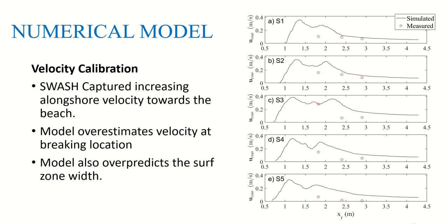And one important piece of information we have to state here is that the model is not perfectly simulating the real case in the lab, because the SWASH model simulates only a fixed bottom, whereas in the lab we were examining movable beach slopes that can have an effect on the results. Also, the model simulation time has been fixed over all storms. However, in the lab we've been doing each storm signal with a different duration.